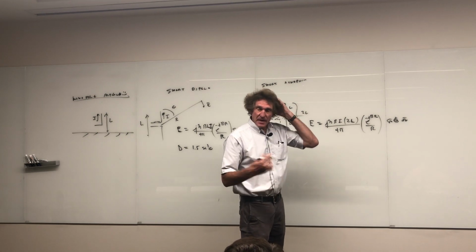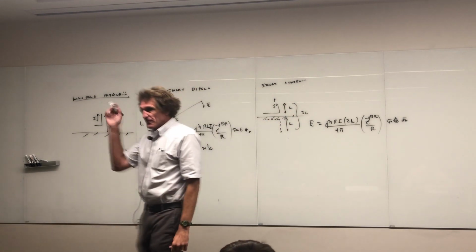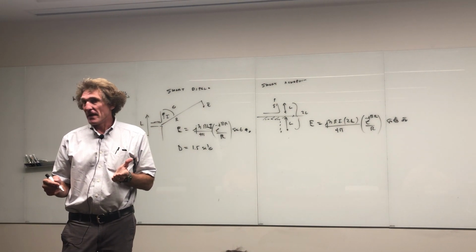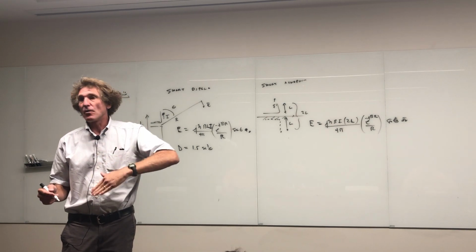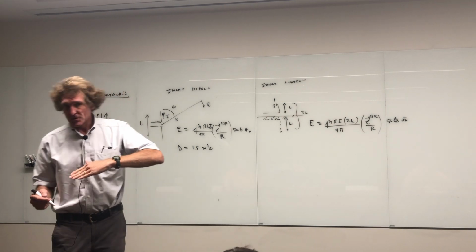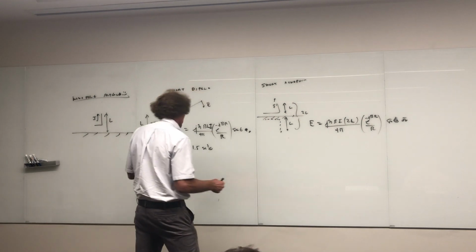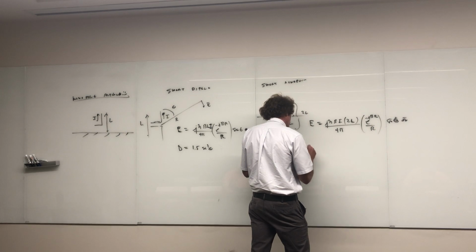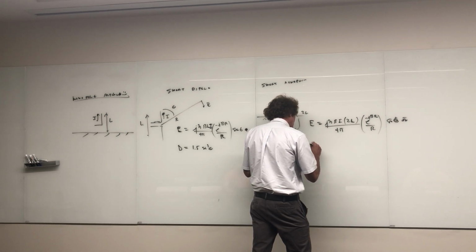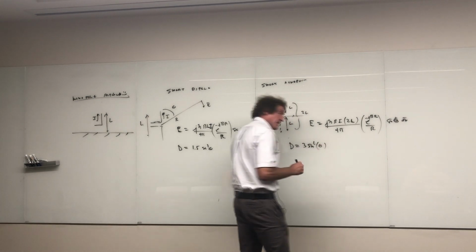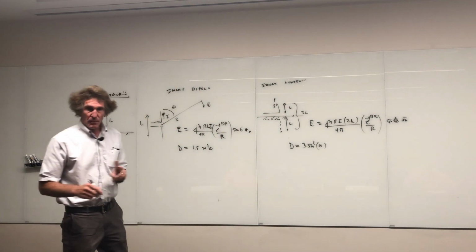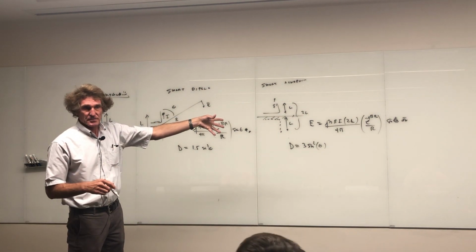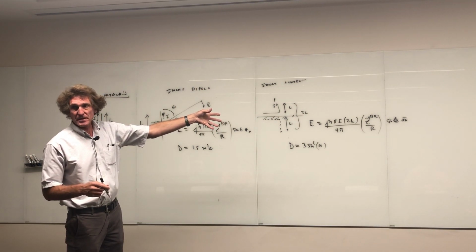If you think about the actual formula for directivity, where you take 4 pi divided by the integrated normalized power pattern, that normalized power pattern is only integrated over half of what it was before, so you're going to effectively double the gain. Over here, your gain, or I should say directivity, is going to be equal to 3 times the sine squared of theta. Now that's a difference. Whatever it is for a dipole, the directivity doubles. Effectively, the gain too. Follow me on this?